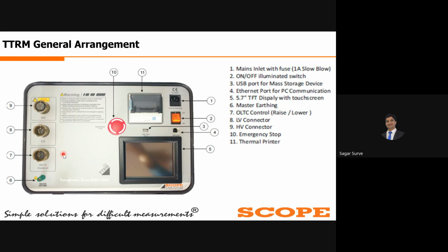It's because if we apply the voltage to the LV side, then as per the transformer ratio, a high voltage may be generated at the HV side, which is not safe to handle or easy to measure directly. That's why we always apply the voltage to the HV side, and at the LV side we get a lower voltage, which is safe to handle and can be measured directly.